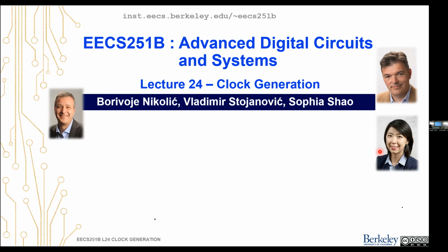And then you want to be able to manage the clock frequency multiplied up on the chip. And also, as we've seen in, for example, the DVFS lecture, we want to be able to scale that frequency to an arbitrary continuous range of frequencies, right? And figure out how to do that in orchestration with the whole clock distribution network and the rest of the compute units in the system.